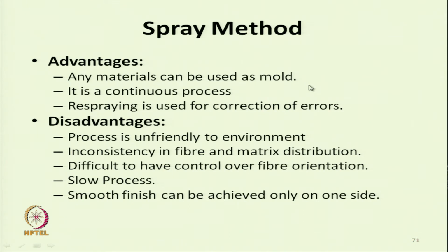The main advantage of this method is that any material can be used as a mold, so we can have very complex mold shapes. It is a continuous process, not like the hand laying method, because the spray gun can run continuously. And in case of any correction required, for any void content or uneven thickness, respraying can be done to correct any error.